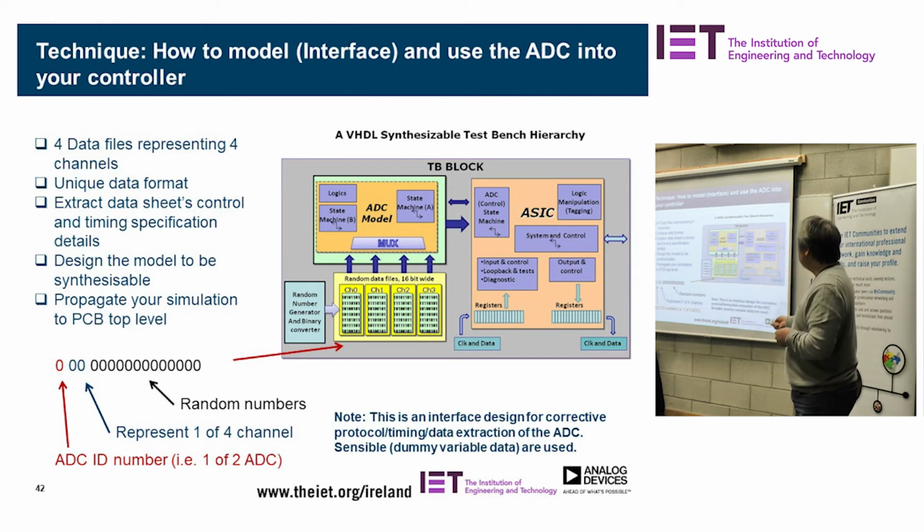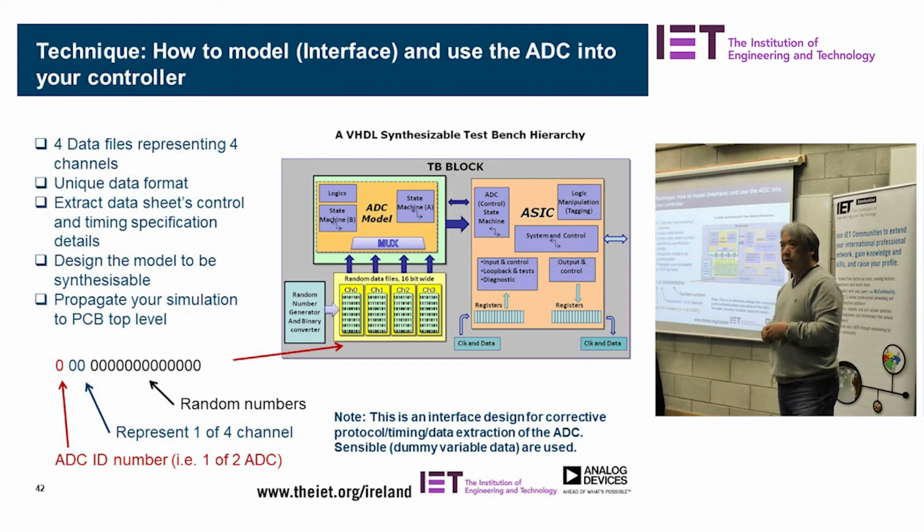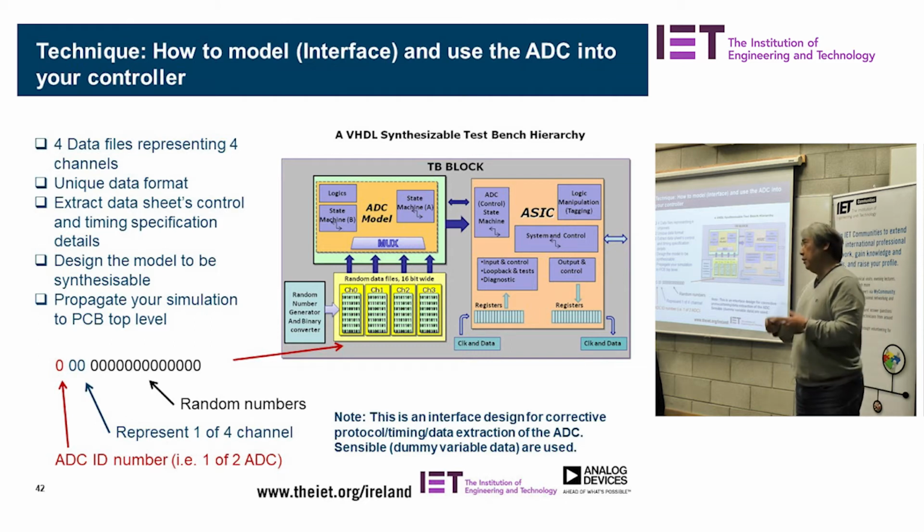So it just shows that it can be done. You don't need the real ADC model, but you need to model it in a certain way, grab the information back and forth, and then check the timing to see whether it meets your timing specifications. That worked out very well. I think that took me about 2 weeks to do, in my own spare time, at weekends and some evenings.